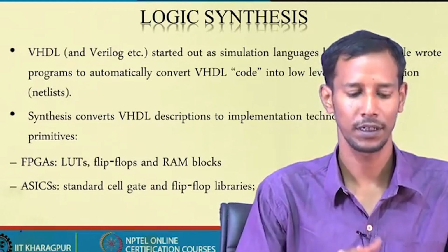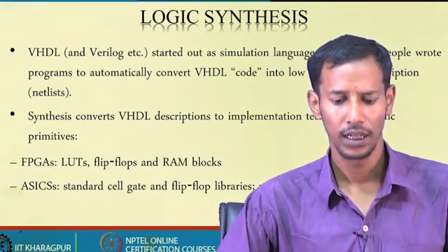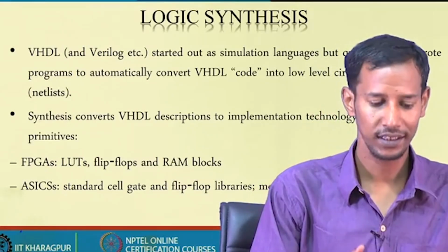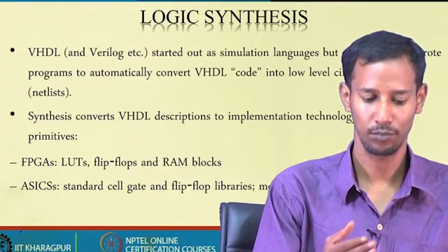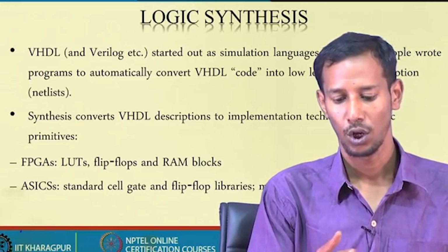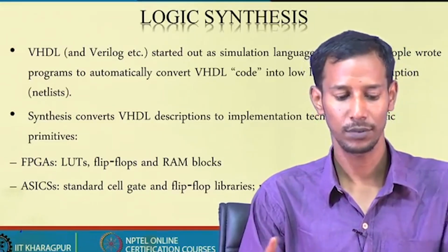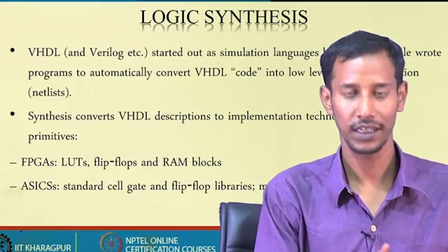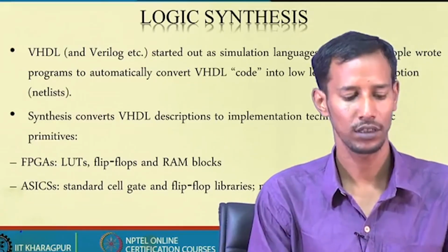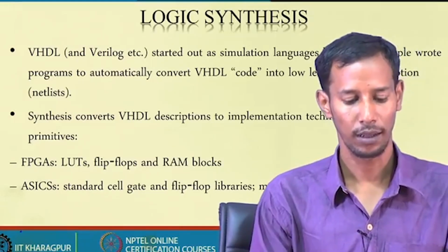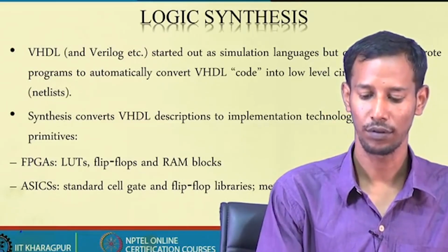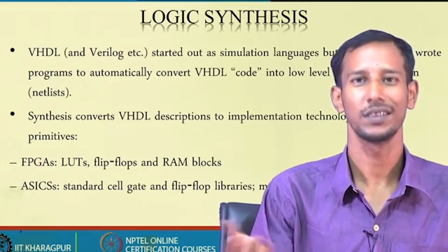Just to add more on that particular perspective, it has to start with VHDL or Verilog. Then the synthesis process basically converts this VHDL description to implementation technology specific primitives. For FPGA it has to be implemented using lookup tables, flip flops or RAM blocks. In ASIC it has to be converted into the corresponding standard cell gates or flip flop libraries or memory blocks if available.